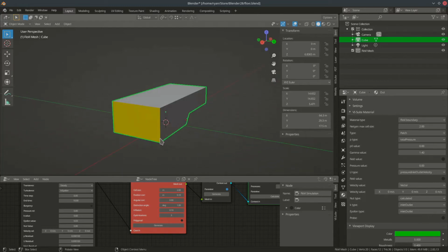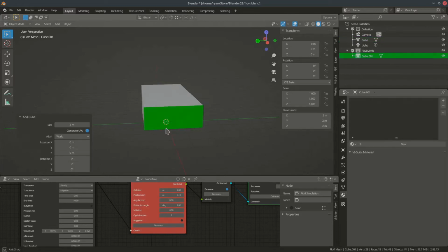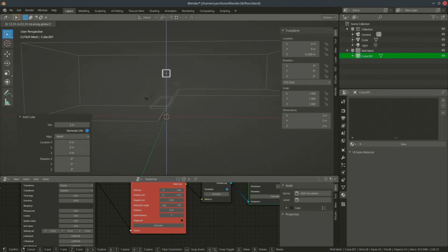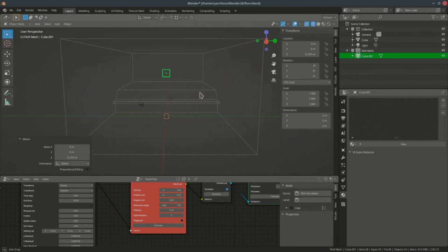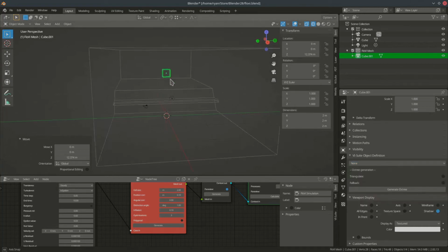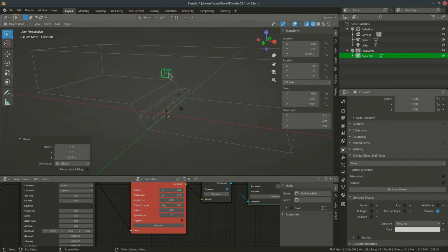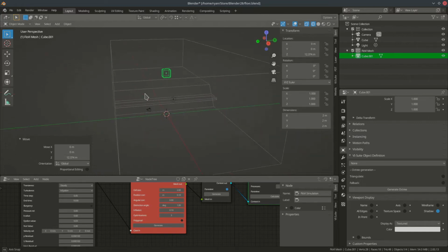So I will just make a quick note about CFD geometry as well as CFD domain. We can also have some geometry. So I've got a little cube here that I just created, and I could put that cube in that space, and then in my object properties I would specify this as CFD geometry rather than CFD domain. And as long as that object geometry is manifold and the basic Blender cube is manifold, then that would be a perfectly valid thing to do. And I would give that a material, and I would specify wall probably as a boundary condition, and that will be part of the simulation.